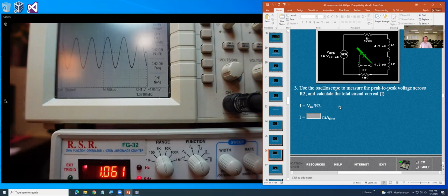So after you get that voltage, you divide by 10 ohm. Then you can enter the value for the current. However, make sure you understand, when you measure, you get around 18.2 millivolt. Then you have to convert into volts before you divide.